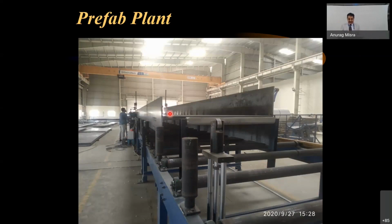for whatever type of beam you are going to create. Now, this example I have taken, especially this flange is 850 and this flange is 450 only. So it is an unsymmetrical beam, which usually in horizontal pull through welding is not possible. So these are the ways now people have created such mechanisms that if you want that, that can be created. This machine itself aligns it, and some tack welding is done while it is moving.